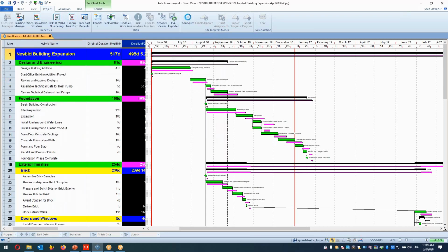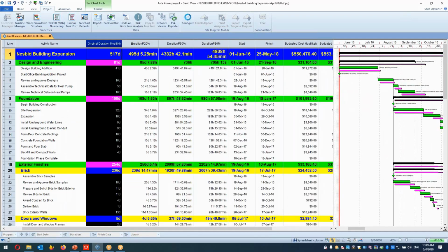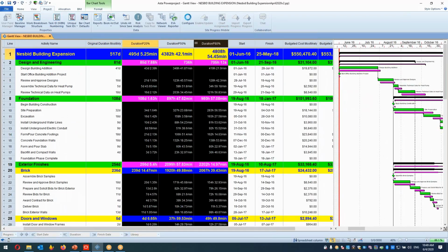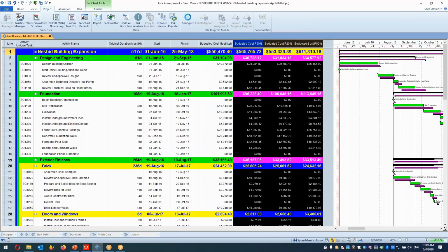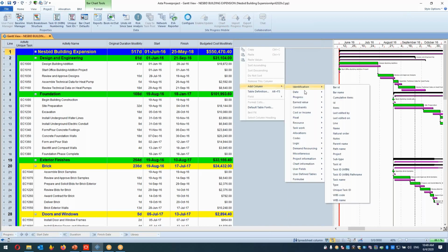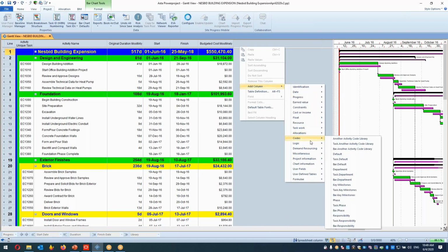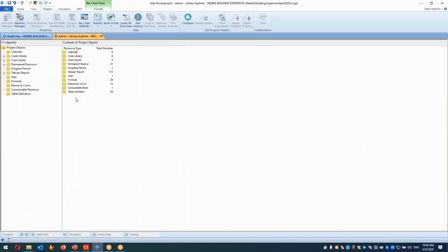So you can create it here. Let me select this duration and lead, and also here duration and lead. We can create it here for the columns, for the codes, and we can call this risk. So you can go to the code libraries if you want to apply risk to individual activities.